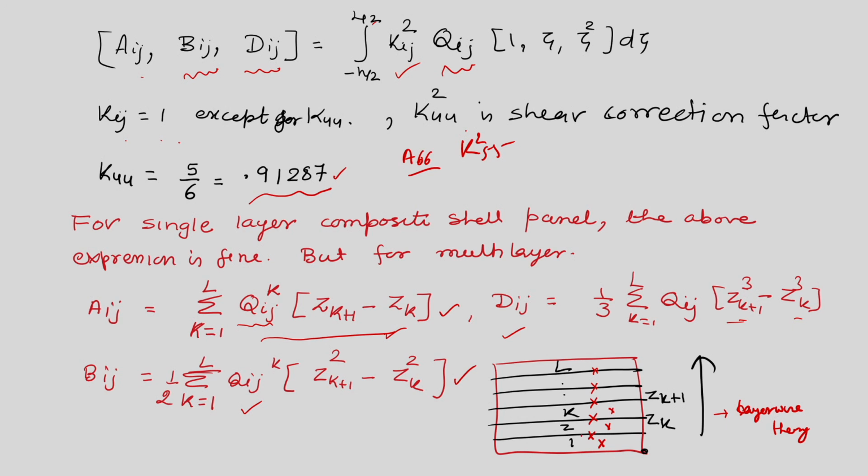In the present case, the variation of u is assumed linear across the thickness and w is constant along the thickness. So, w0 and ui, I can say u1 and u2. But in a layer-wise theory, in each layer it is linear, so it may have some kinkiness, so it can represent the local behavior.